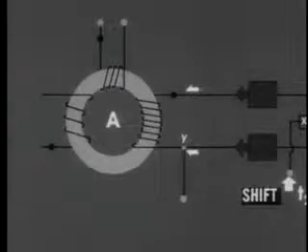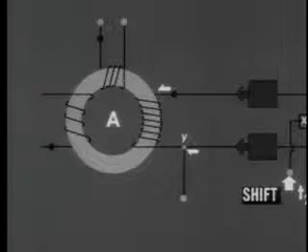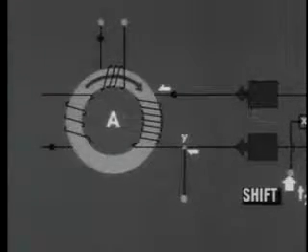The upper branch, however, does reach core A, entering its output winding as a dot pulse. Since core A is in the binary 0 state, that is, its magnetic flux is already negative, an additional pulse of dot current will have no practical effect on the core. There is a counter EMF induced in the winding when the pulse is applied, but because the change in flux is so slight, the counter EMF is negligible.